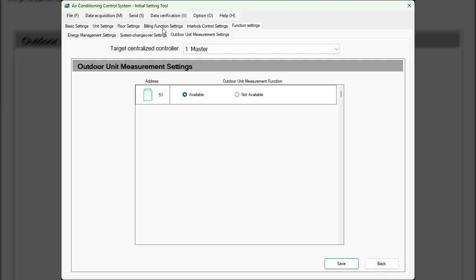I turn that on, and then now I'm going to send to controllers. So save it, and I'm going to send to all controllers. And so the username is initial, just like we're used to, but the password is going to be init with a capital I-N-I-T. And then the password also includes the DP, digital PIN number, or that's just the serial number. So let's say this master controller is 251226 is the serial. That would be the password. I hit OK, and then now it'll go out and push this file into those central controllers, and you're done.